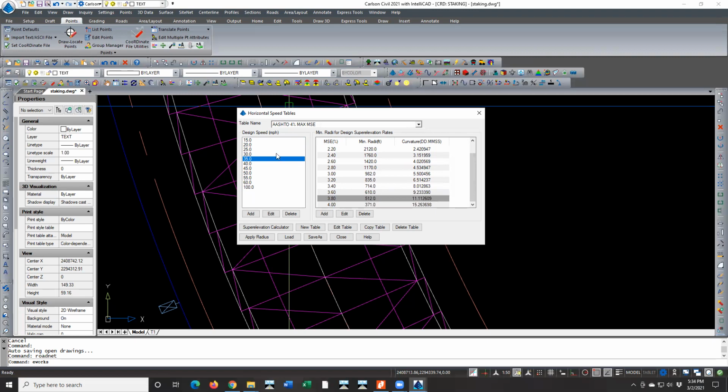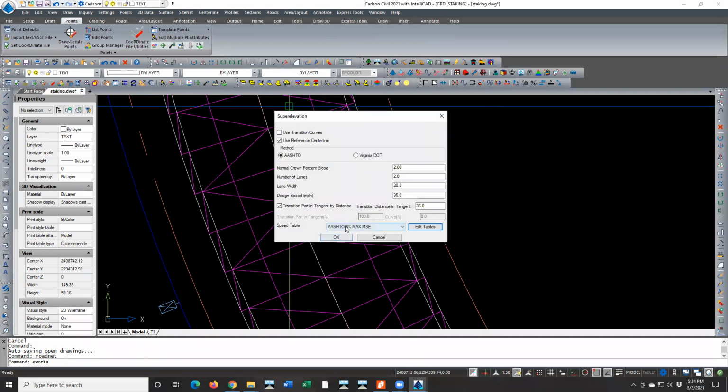Now what happens when you do these, by the way, just so you understand how these work. If I say this is my maximum super elevation of 4%, then what it does is it forces the length of the super elevation to be longer. Otherwise, if it lets me take it steeper, I can get around the curve by shortening that up, but go into a higher bank rate. Any of those are well and good and fine. And what do you say that you're held to 4%? 4%. Yep. All right, so let's switch it to that and let's see what we get.